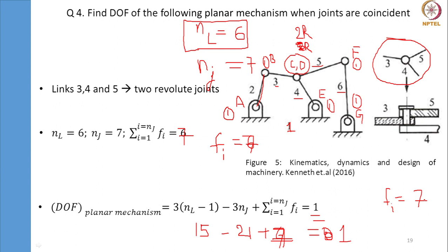Sir, are A, E, G the same type of joint? A, E, and G, yes, they are pin joints. All are pin joints, all have 1 degree of freedom. Sir, are pin joint and revolute joint both the same term? Pin is the one where it is attached to ground. Revolute is if it is attached to another link. Both will have a single degree of freedom.